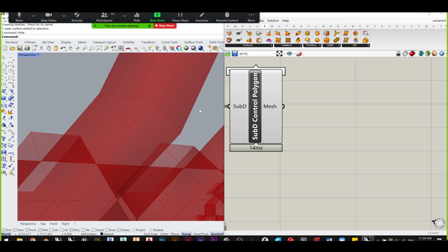Meaning that if we just use mesh join, and we join these two guys up together into one mesh, those points where Bob and Timmy are meeting are still going to be duplicate points, right? They're not going to be merged into one point because join and merge is not the same thing, or join and weld is not the same thing.